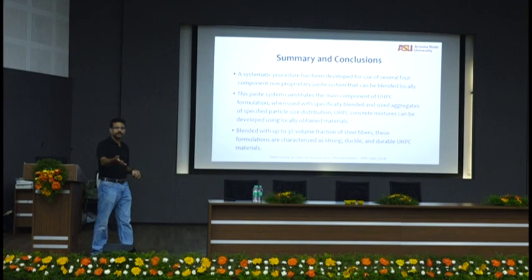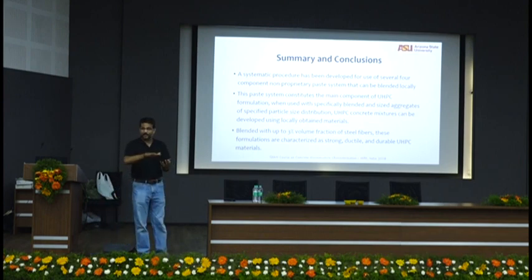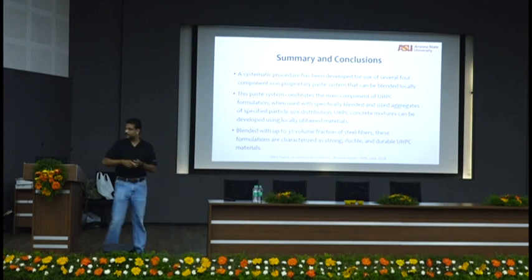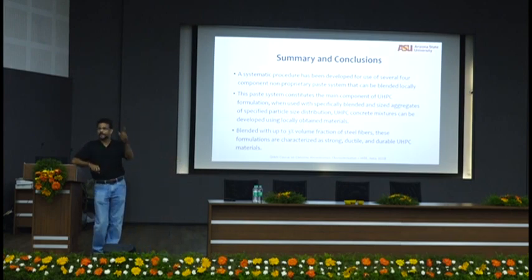You can't just stick it under any compression testing machine and test, because the flatness affects the performance extremely. So you have to level surfaces, and then do the test on a strain control system so that you can get the entire stress-strain curve. So it was implemented, and it's one of the first non-commercial UHPC bridge decks that has been implemented in the US, and at much lower cost.